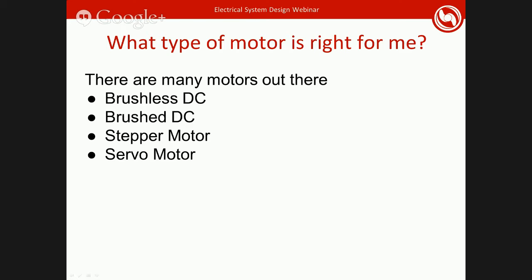In order to get around this, depending on the application you're using, say you don't want to be constantly applying power to it, you could add something such as an absolute encoder in order to be able to return the stepper motor to a specific position. Or you could have some kind of mechanical solution, such as a block, which says, I'll reset my stepper motor to this position, and then always reference that. Those are a couple of things we've thought of in the past.